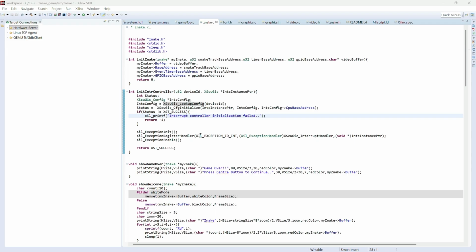The hardware software synchronization was another issue that I faced. When I introduced special prey, the snake was not detecting it. The score was also not increasing, and even the size of the snake was not increasing. Then I found that I was only drawing prey using software but not updating the hardware. To solve this issue, I used the draw prey function. This sends the prey position to hardware and draws it. Now both the hardware and software stayed synchronized.